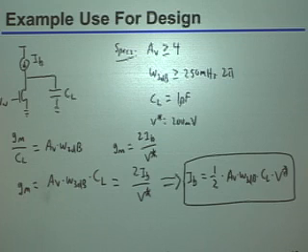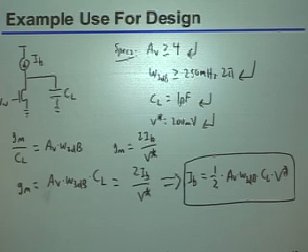Ballpark, I don't need the exact numbers. Close. Actually, I think you might be right. So basically, this right here is about a gigahertz. A gigahertz times a picofarad is about 1e minus 3. This would divide that by 5. This multiplies it by 4. So, okay, yeah, it's about 800 microamps, something like that.